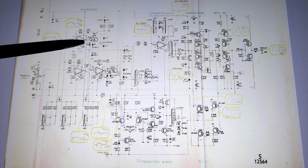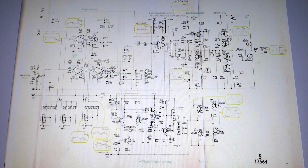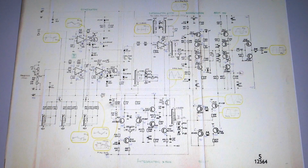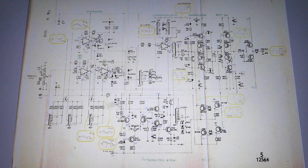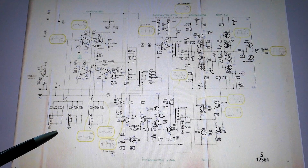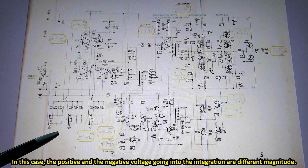But because rotating these op-amps had no effect, it could be some of the diodes or transistors, but I already measured the diodes here, so this is almost shrinking down to just these transistors or maybe some resistor, but low power resistors don't fail often. These two transistors, TR-15 and TR-16, are the most suspicious now. And by the way, these sections of the waveform selector can select the non-50% square wave or the sawtooth with the faster rise or faster fall.